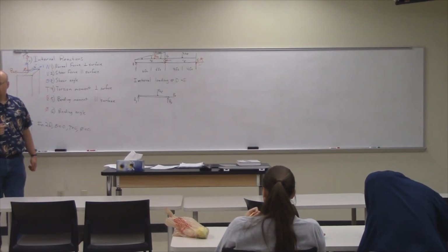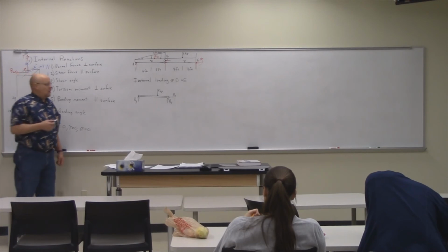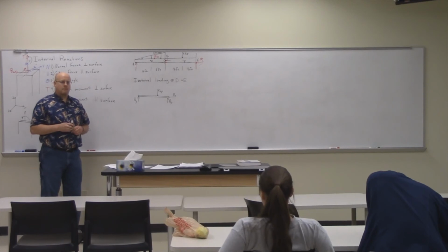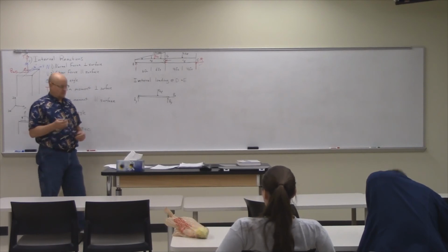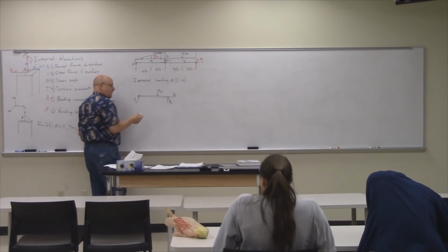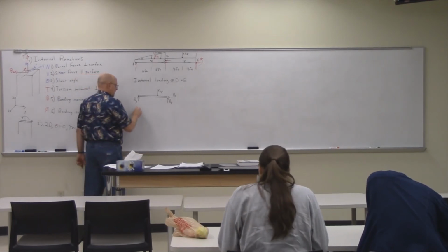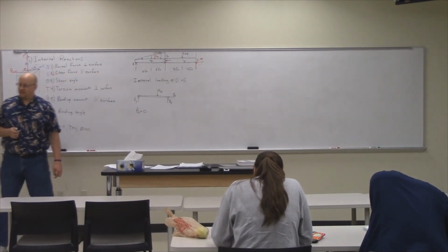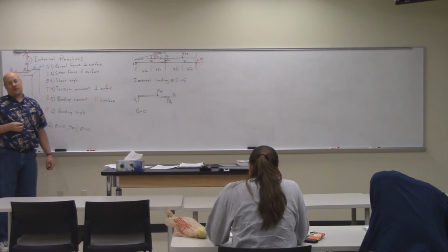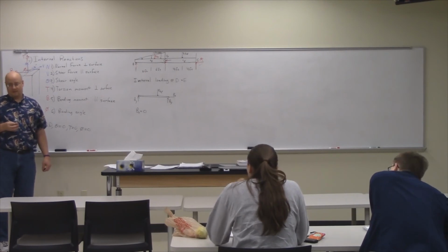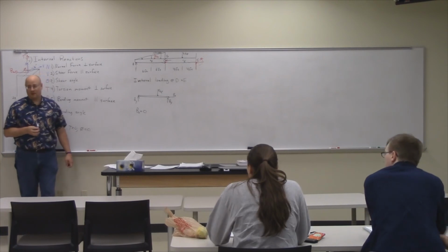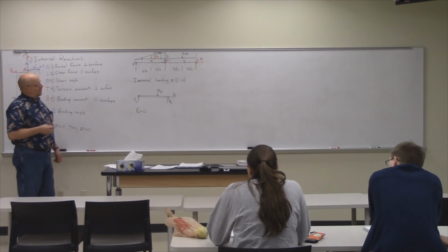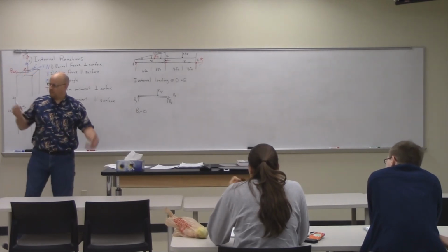Sum of the moments and forces equals zero. All right, so what do you want to do first? Well, Bx is the only one in the x direction, so you can sum the forces in the x direction. So we look at it and identify that Bx is equal to 0, by inspection. If you say by inspection, you better make sure that it's legit. You don't look at the picture and say, oh, well, by inspection, D equals 6.24 kips.